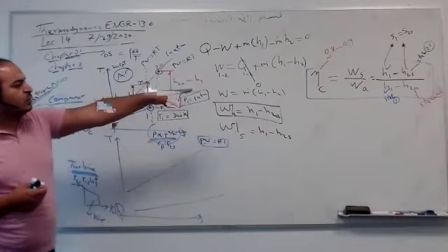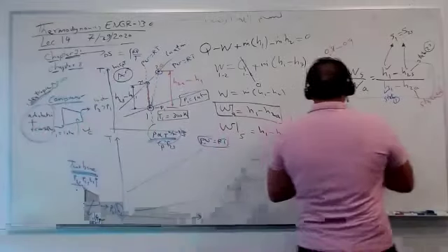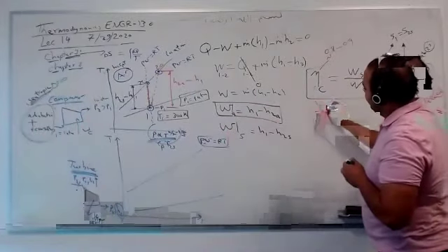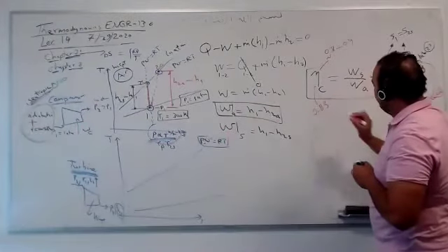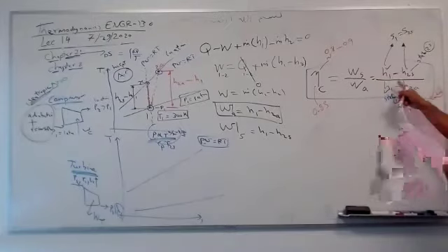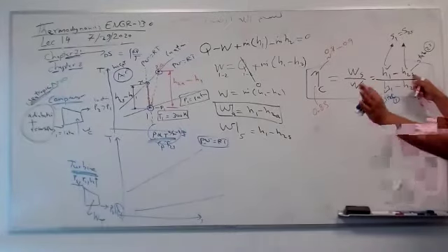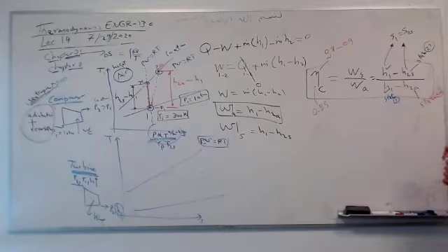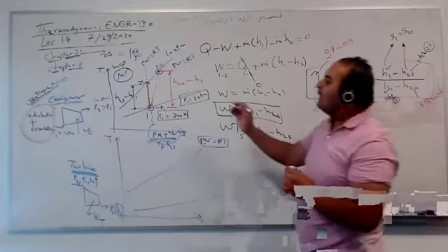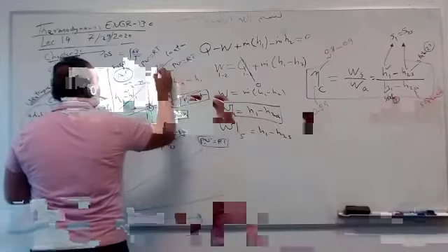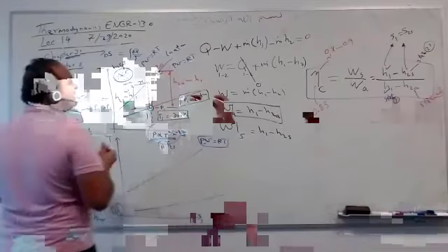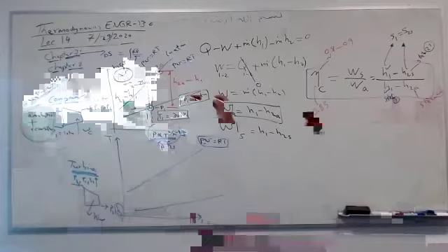For 2A, if you have the compressor efficiency, let's say 85%, you have H1 and you have H2S, because 2S is known, so you can get H2A. So you can know exactly where this point is. How much work do you need for this compressor to compress from 1 atmosphere to 10 atmospheres?